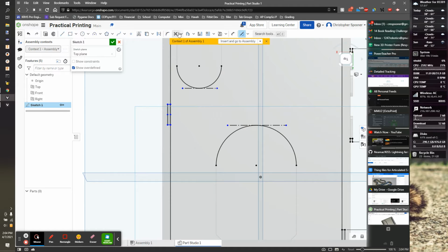Good. Now I can pull a dimension between these. I can't change this dimension, but it will give me some number. I'm going to copy that number, and then I'm going to dimension this to here to be Control V divided by 2. So that is exactly halfway between the two, which is not where I thought it would be, but that's what happens to actually exist.